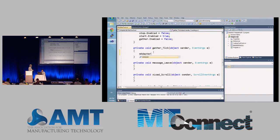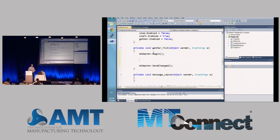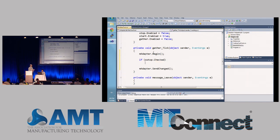And under gatherTick, now what he's going to do here, he's going to type in this adapter begin. Again, that's to start the process of looking for any kind of conditions that are throwing faults or warnings to add those to the alarm table. And it will also check to see if any alarms that have been added have been cleared. So it does the mark and it performs the sweep function for you.